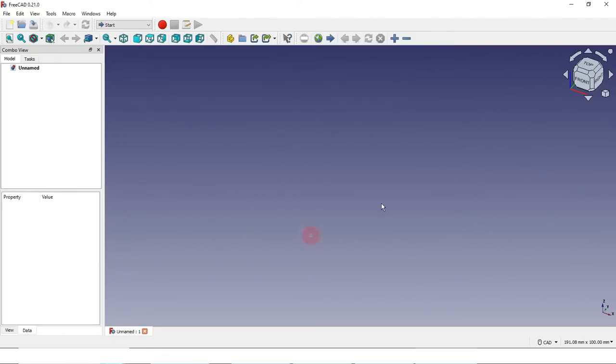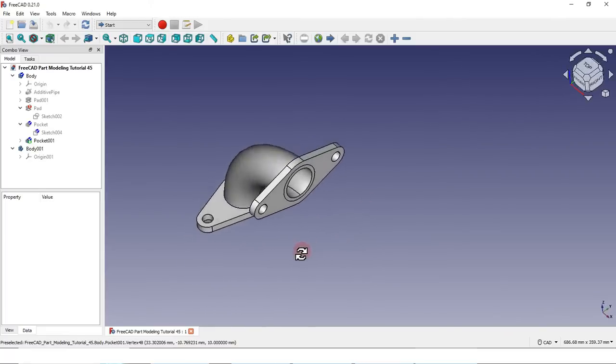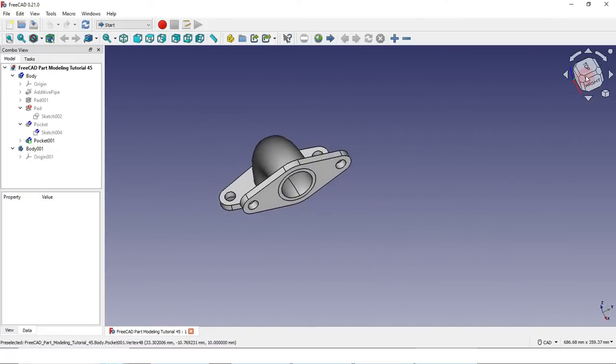Now we will head over to the cube section. To understand the cube section, I will open one of my 3D models and show you. So here I have opened one of my models, which is a pipe with flange, and now if you click on the cube here, then you will get an option of isometric and perspective views.